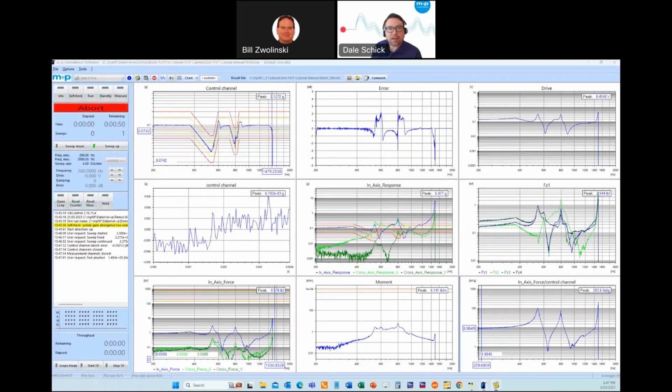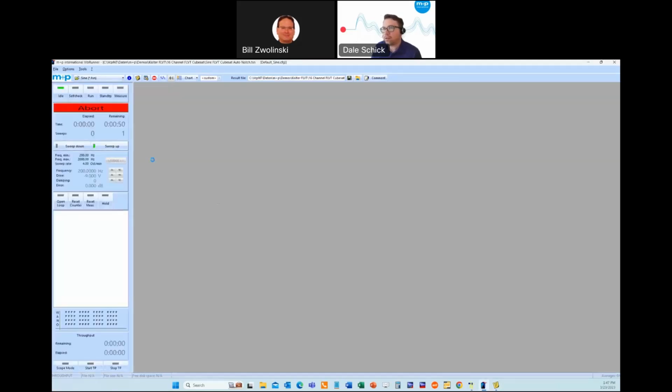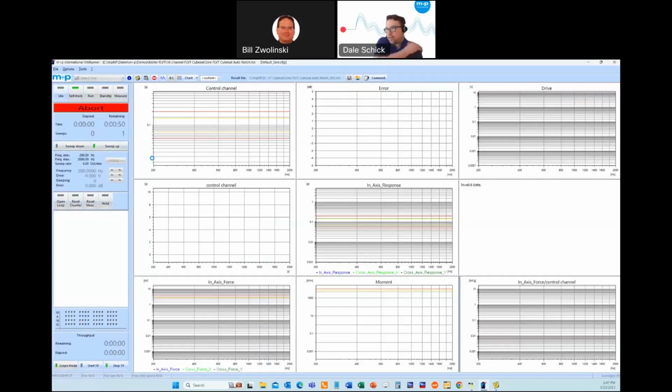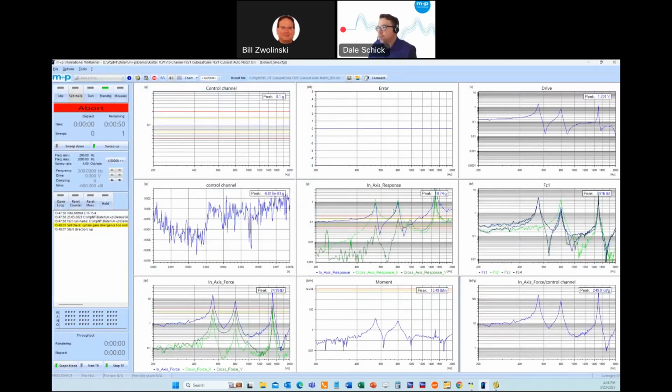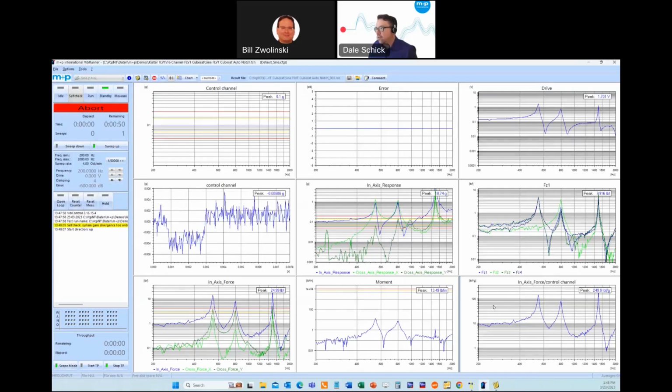So I'm going to open the next test profile, which is almost the same as what we showed before. Go, loading. This is going to put out the same self-check, but you see here, now we just have 0.1 G straight across. This is a really simple test profile. This could follow some shape for a test specification. It could be random, it could be sine. And either way, we still get the same in-axis response.